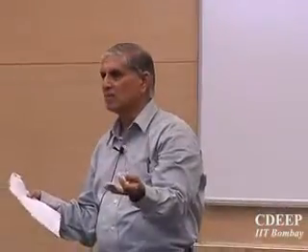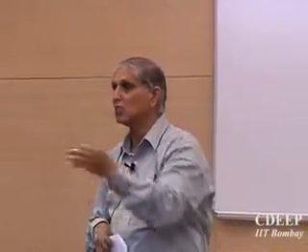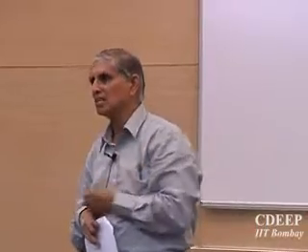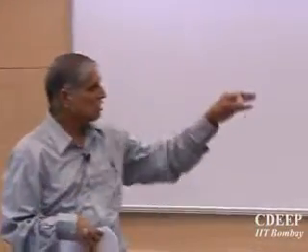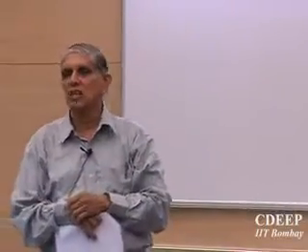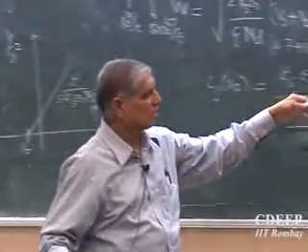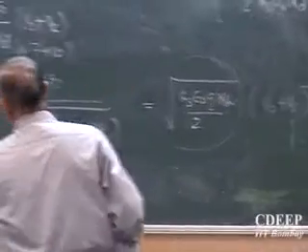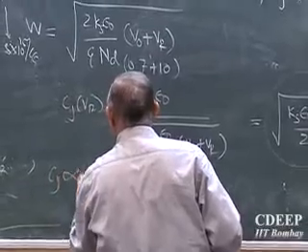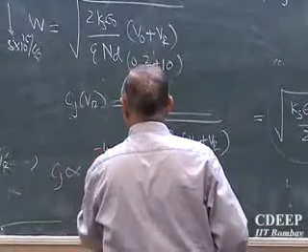That's how we do it when you make a device: we monitor again and see what specs we wanted, and whether we are meeting them. So with this capacitance voltage curve, you can see that C is proportional to VR to the power minus half.